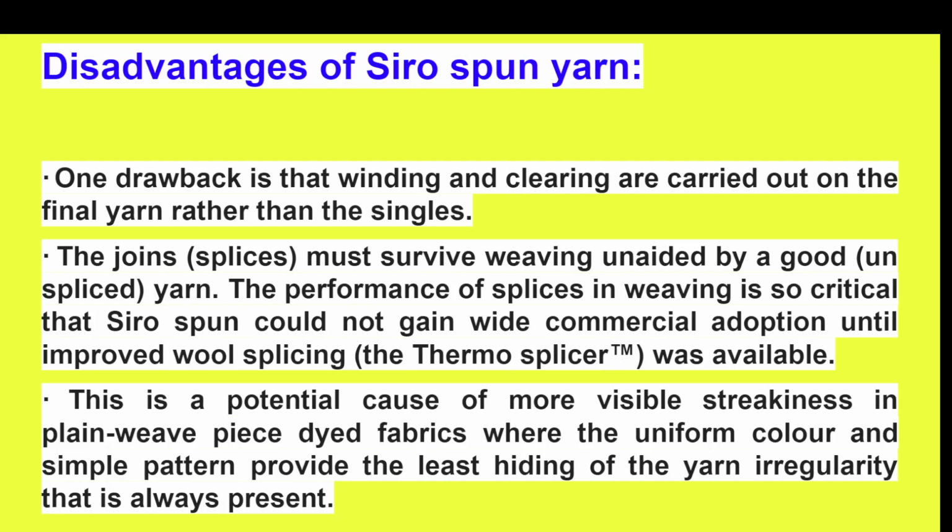It means if we make a fabric with Siro spun yarn and we dye the fabric in piece form, then after dyeing, streaks appear highly in the fabric. Even if we use simple patterns, the yarn irregularities cannot be hidden with the help of color patterns.